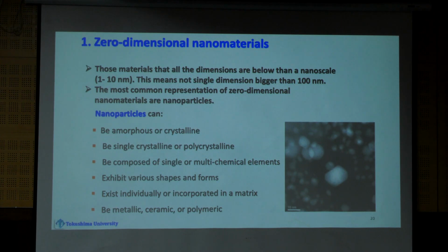They cannot bind together. And crystalline is a solid crystalline material, like sugar has a certain shape, graphite has structures. So if you measure their XRD, you will get a strong peak. But if you measure the amorphous one, it will not be a sharp peak. It will be a hump kind of structure. So this is the difference between amorphous and crystalline. So those particles might be amorphous or might be crystalline, but they are zero dimensional.